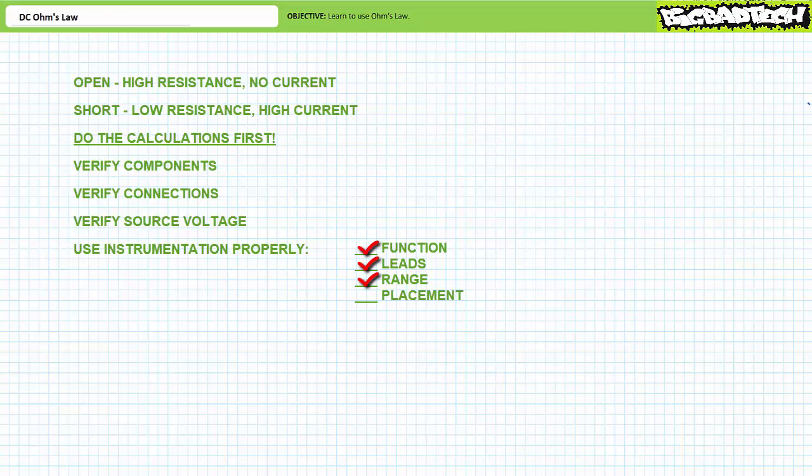Range. If your DMM is not auto-ranging, one must manually choose an appropriate range to obtain the most accurate measurement results. Whereas if your DMM is auto-ranging, your DMM will automatically pick the most appropriate range to obtain the most accurate measurement results. Related to range, be aware there is a limited range a meter can safely measure. Do not exceed this range or you will damage the meter and/or yourself in the process of doing so. Certain levels require appropriate levels of PPE or personal protective equipment to measure them safely.